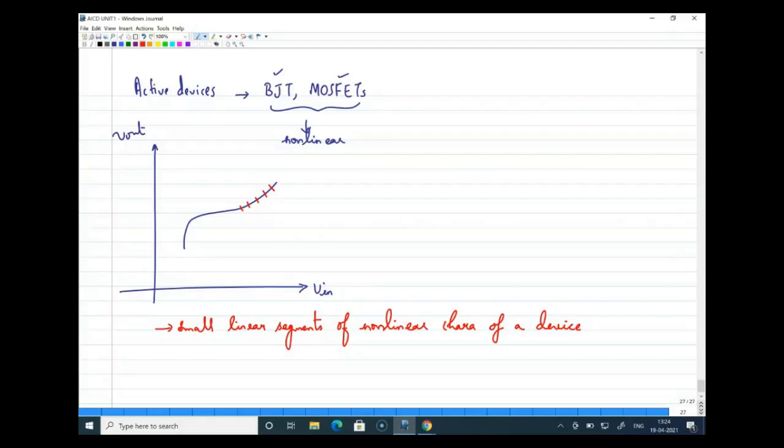Some of you will definitely remember when you were performing the experiment of the RC coupled amplifier. You would have seen a distorted output, or a clipped waveform, when your input signal is very, very large. And the faculty or the teacher who handled your class would have told you to use your input amplitude in this range, to keep your input amplitude from 20 millivolt to 50 millivolt.